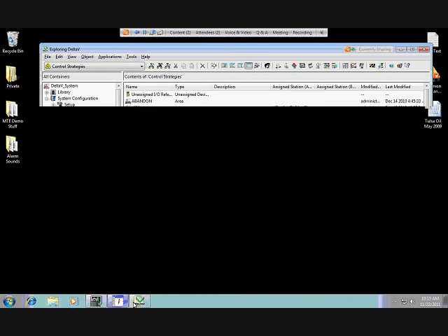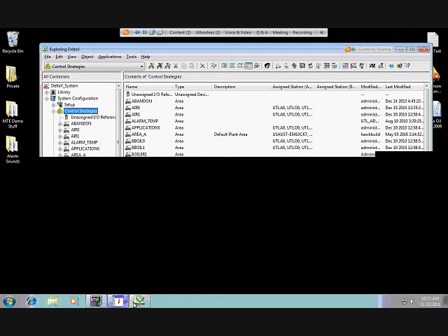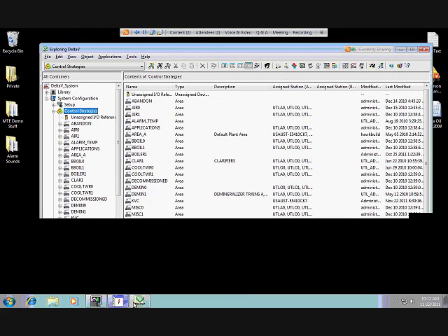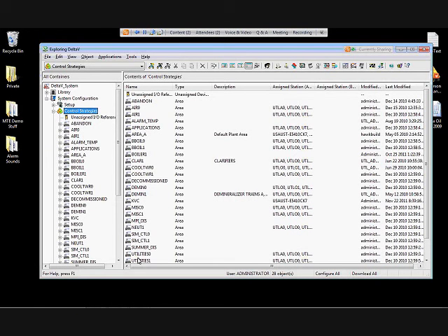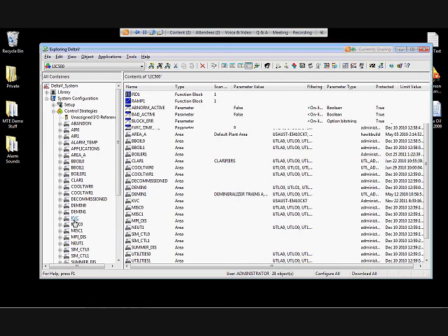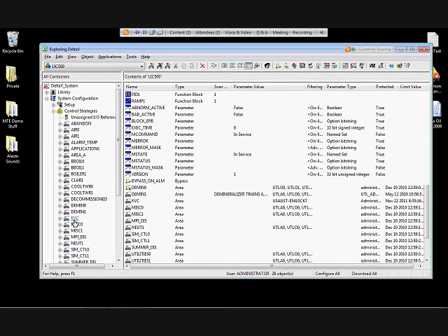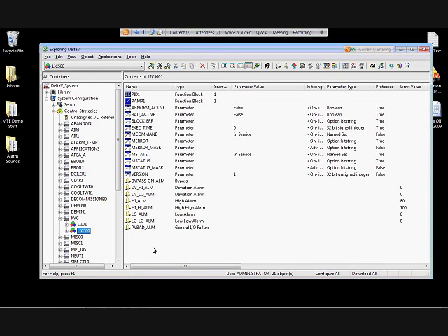So going to DeltaV Explore, this is the heart of the engineering environment for DeltaV. That area KVC was throwing the most alarms, and within that you see there is this LIC 500 module. I recall that the high alarm was actually the one that was generating most frequently. I expect that it might be chattering. So I'm going to just take a look at its properties.